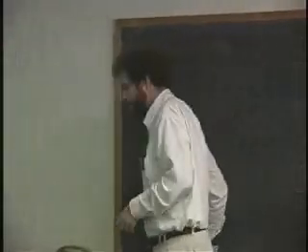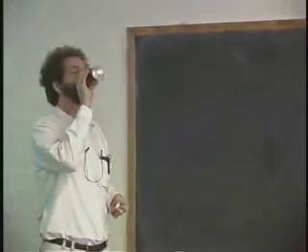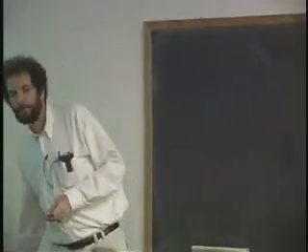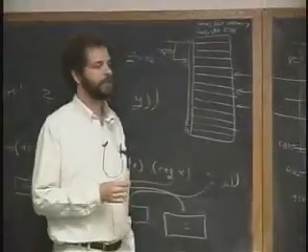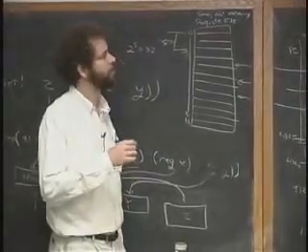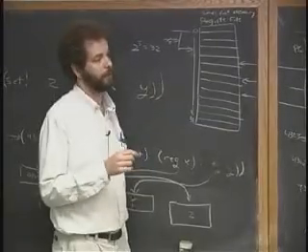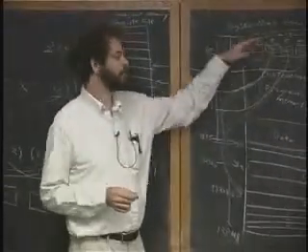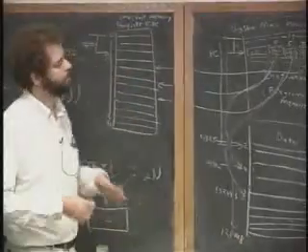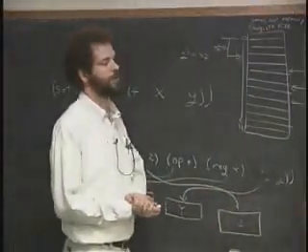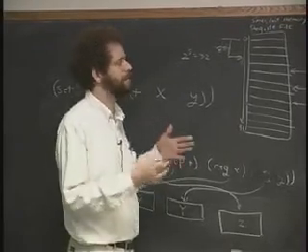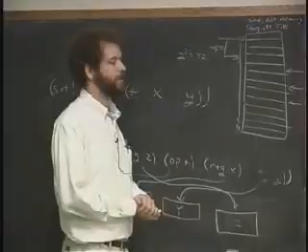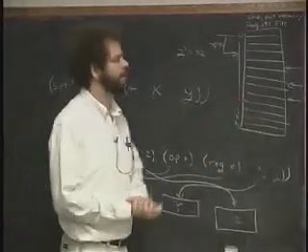Now, each of those blocks, each of those 0 through 31 blocks, is actually the register that contains the data? Mm-hmm. Absolutely right. And do those have a width, maximum width? So it turns out what we're going to do in this class, now modern machines are beginning to move from 32 to 64, both in how wide things are and also how long they might be. But for now, at least for the next 5 years or so, it will probably be stuck with 32. So that's how we're going to teach it now. But just keep in mind that there's nothing magical about the number 32, and as a result of Moore's law, it's going to grow pretty soon to 64.